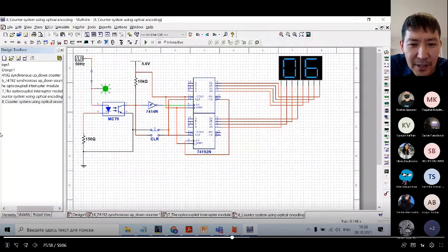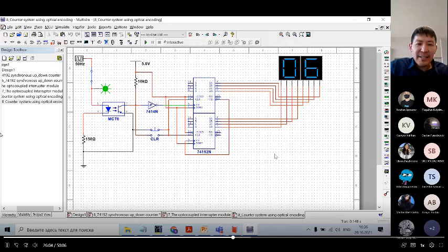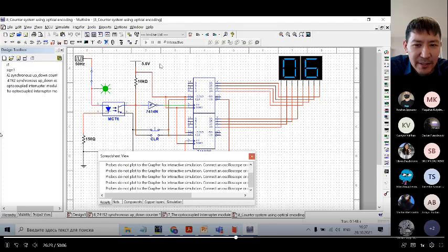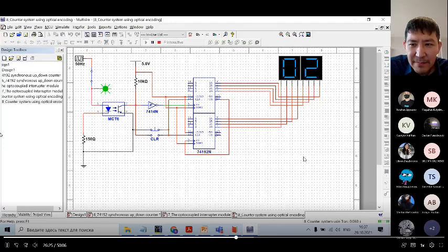You can connect to the clock of the second integrated circuit, and actually you can increase the range. At first it was 4-bit, but by cascading and connecting them together, now you can see I can count 8 bits, right? So for example, let's imagine that people go through this door, and I can just count this amount of people.